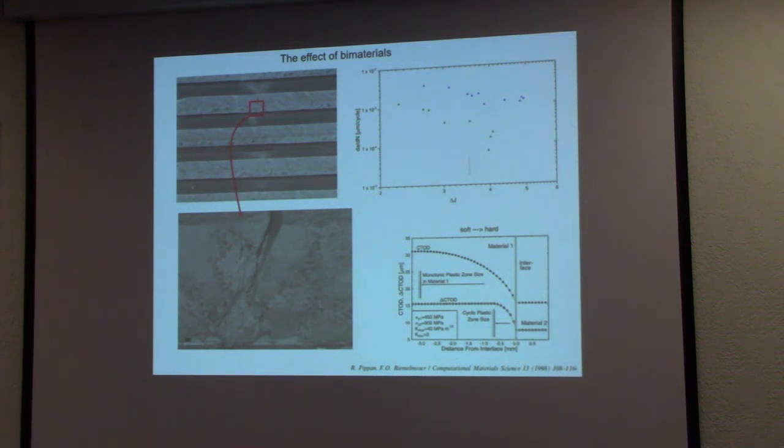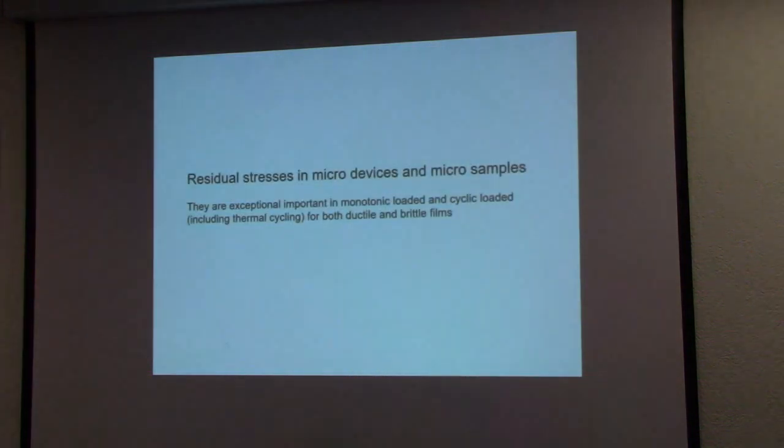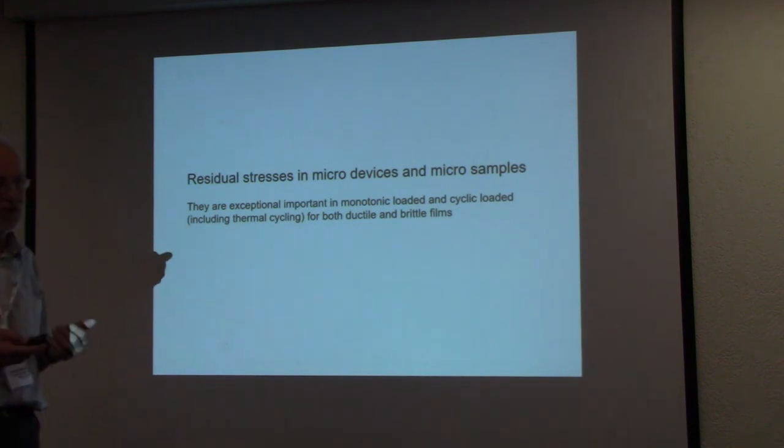For many components, the residual stresses are really required, otherwise they would not work. For example, many of the hard coatings require high compressive stress in order to do their functions. And the high stresses can be generated by thermal treatment or by the growing process, usually.